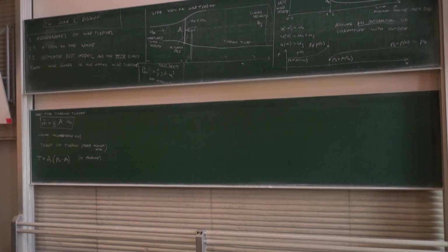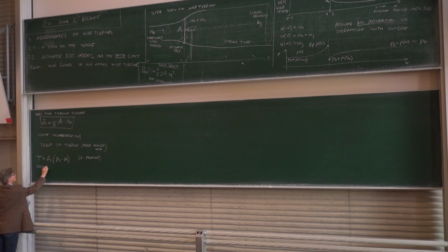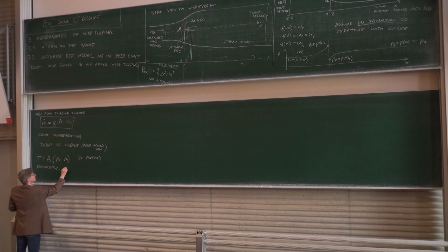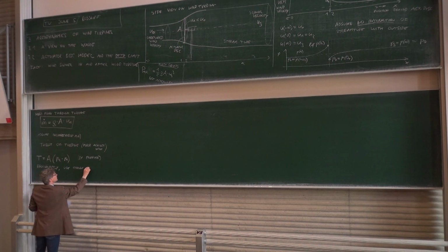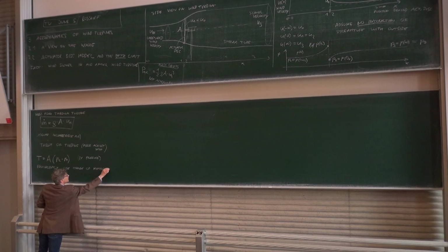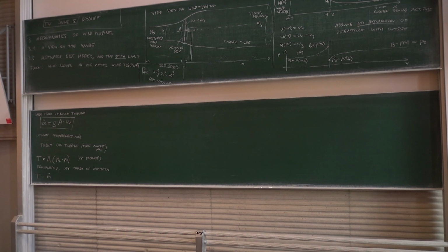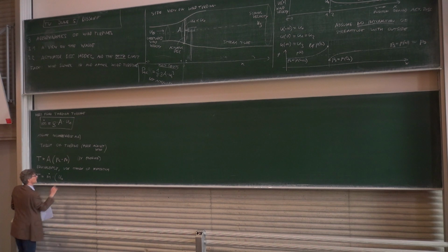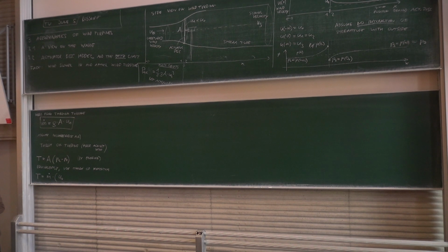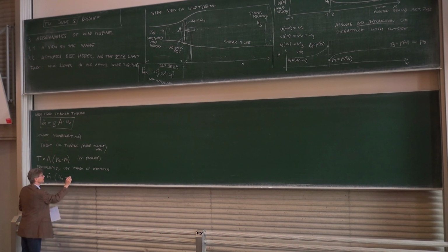And now by change of momentum, we could get the same. Equivalently, use change of momentum. So let's use change of momentum, and then we also get thrust. So thrust is the mass flow. How much mass gets changed momentum? If there wouldn't be a dot, it would be just momentum. But if you change momentum, then you get a momentum change per time, and that's actually a force. So what we have here is m dot, the same quantity that we have up there. And then we need, again, to have a positive number. So it's u0. That's this momentum we had at the beginning, and then it gets slowed down due to this thrust of the wind turbine, and it will have at the end u3.